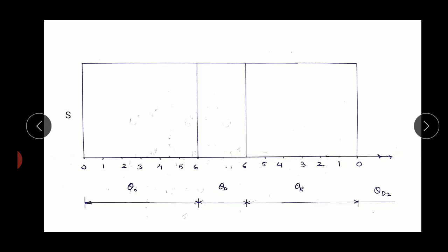Now the displacement of the follower during the rotation of the cam will be given. Plot it on the y-axis. Suppose it is 40 mm or 50 mm, or 60 mm, whatever it may be. Draw a line equivalent to the displacement of the follower. You have to choose a different scale for the y-axis and a different scale for the x-axis, because on the x-axis we are plotting angle turned and on the y-axis we are plotting displacement. As both are different terms, you have to choose different scales for both.